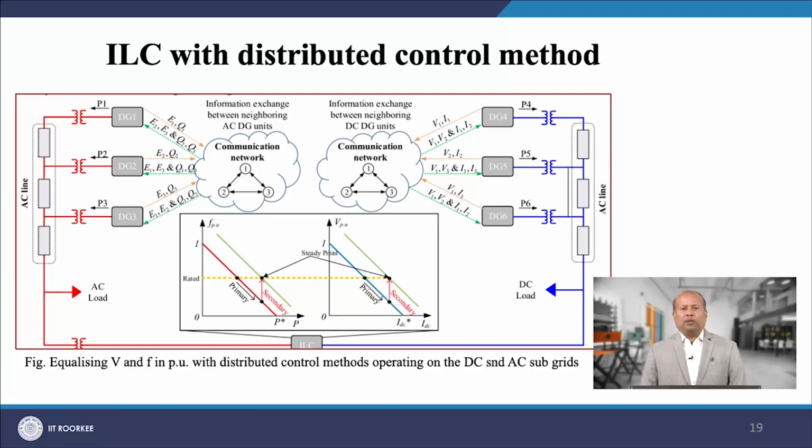The requirement of distributed control over decentralized techniques arises due to unavoidable power mismatch because of dissimilar line impedance. To achieve global accurate power sharing among multiple distributed generations and storages in hybrid AC-DC microgrids, the local variables of neighbor distributed generations and storages need to be transmitted through peer to peer communication. The received data can be used to adjust the local variables accordingly and achieve global power sharing.